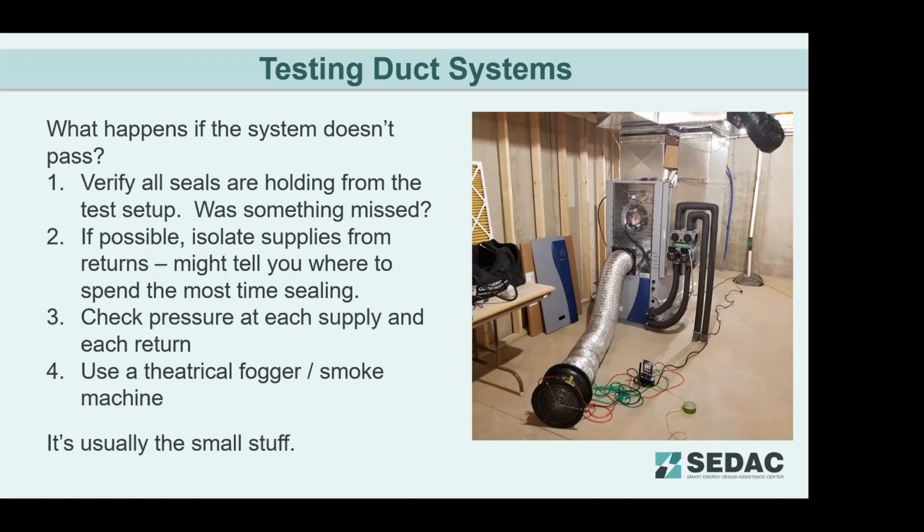Well, I mentioned earlier, you can pressurize or depressurize the system. You're going to get the same leakage rate. I tend to prefer the depressurization because it sort of pulls the tape up against what it's trying to seal to a little bit. If you're pressurizing it, it tries to kind of push out or balloon out. But I've done it both ways, gotten the same numbers. So it's really a preference.